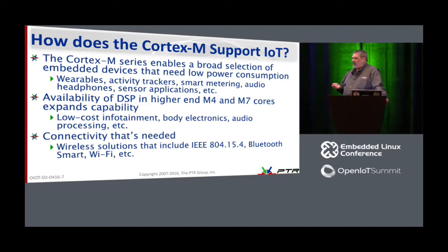And for the IoT, when we're talking about wireless interfaces, this is a big deal for us because it means that we then don't have to go through FCC certification. But these radios also have stacks built into them. So our small processor, our Cortex-M0, for instance, with 32 kbytes worth of RAM, trying to get a full TCP stack, something like that, is just not going to fit all that well. It can. I mean, you can certainly do it, but you're really using a shoehorn to squeeze it in. On the other hand, we can put the stack in the radio and have the radio interface be a simple UART, SPI, or I2C, and then our small Cortex platform doesn't really have to do anything as far as the stack is concerned. We simply talk to the radio, and the radio implements the stack.